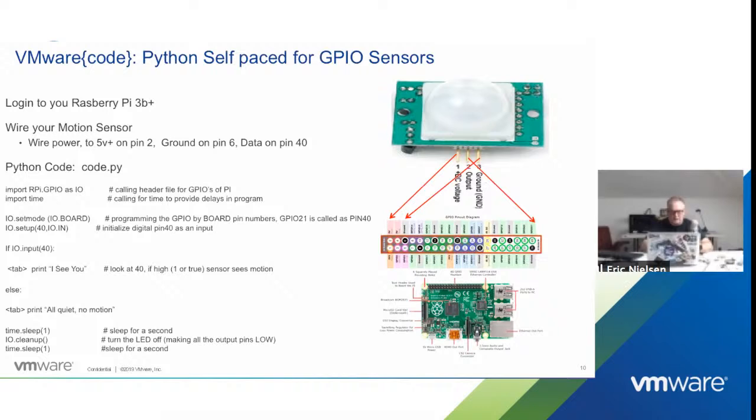Then I'm going to hook that to my Raspberry Pi. I'm going to grab 5 volts on the first pin there, which is easy to do. I'm not actually going to run this, but that's it. Just put it on there with these little female jumpers. The third pin is the ground. Make sure you're not hooking power and ground up wrong. I've never had anything burn out by just hooking GPIO wrong, but if you reverse power and ground, you have a shot of burning out your sensor.